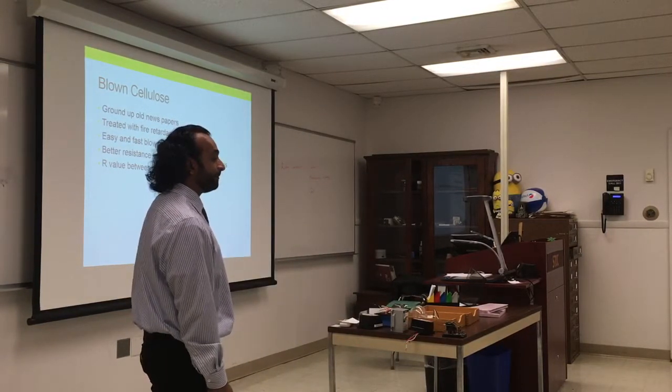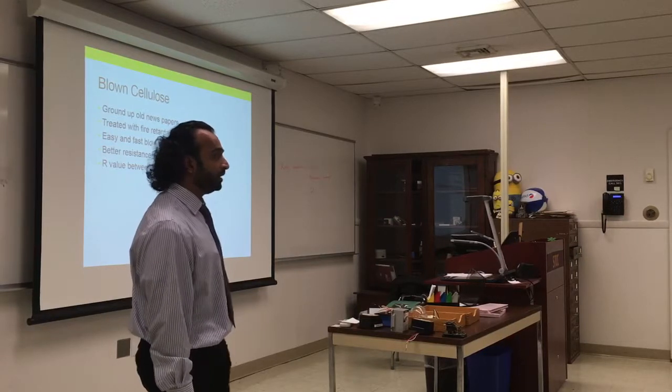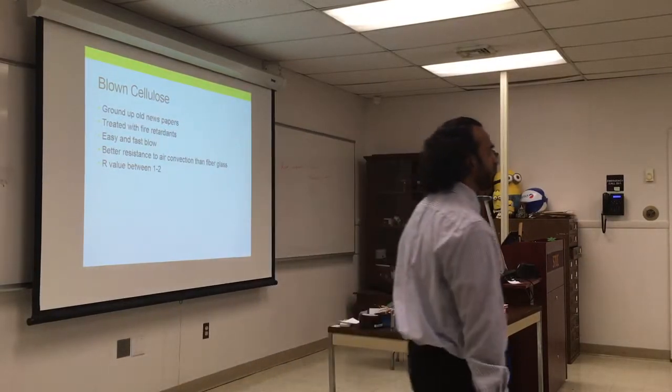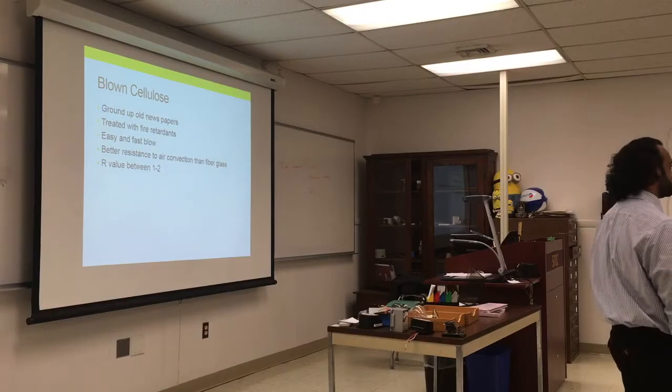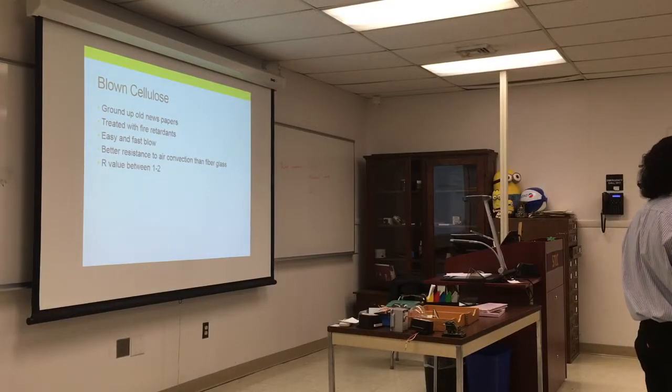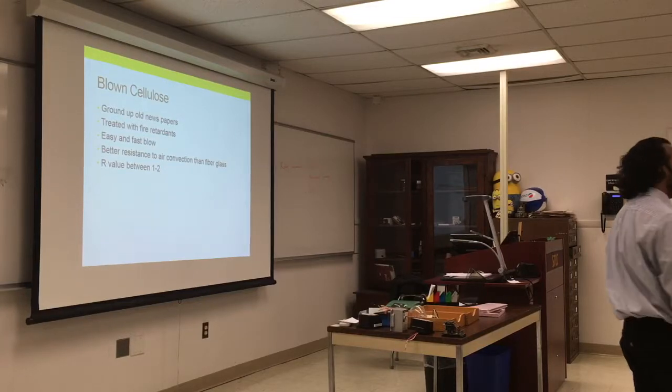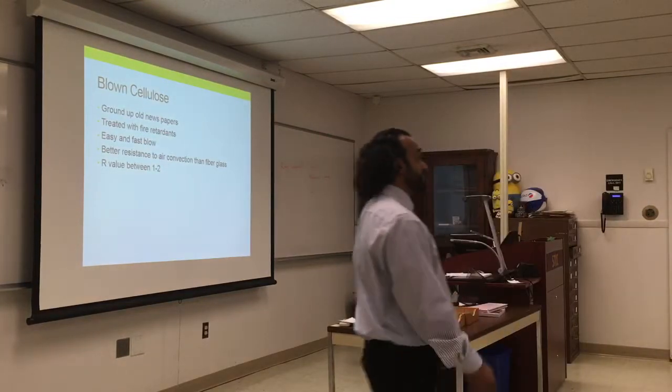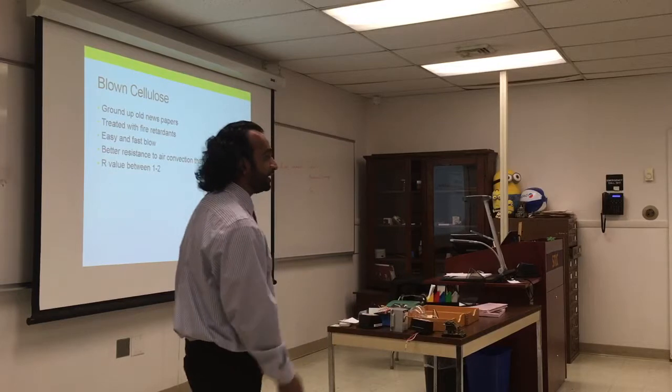But where's that rate, that trade-off? There's a calculation you can make based on the installation, and also how much it will cost you. If it's possible, you can fill the entire attic with insulation, but it's going to cost you a lot of money. And how much are you saving by that? So there's a rate of return on the investment.